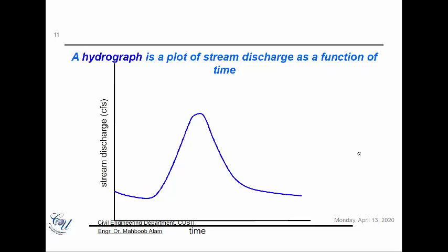Hydrograph is basically a pulse of a certain stream. In fact, the discharge in itself is a pulse of the whole catchment. So whatever is occurring in the catchment, you would be able to find out in your discharge. If you have a very good record of discharge with a relatively higher time resolution, sometimes even small changes in the catchments can be observed by just looking at the discharge data.